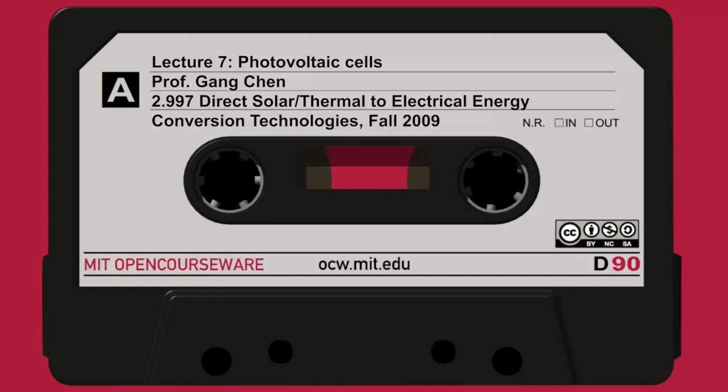When current is 0, that's the open circuit voltage. It's like you're shifting the diode curve down in parallel. If you don't have light illumination, it's just the diode equation. So just shift that diode curve down to the negative, the forward branch.